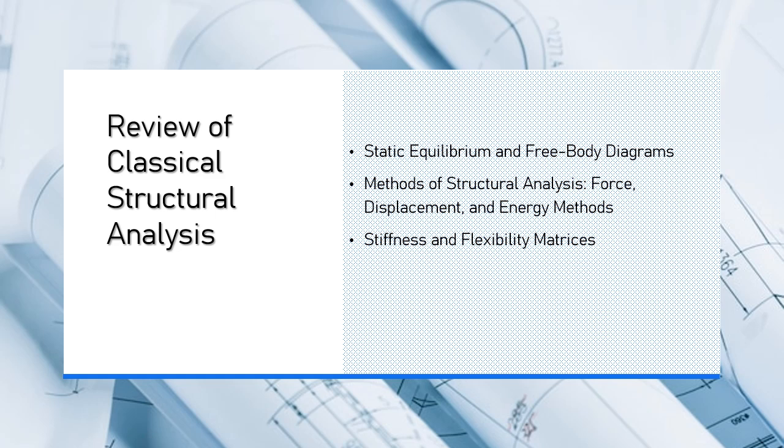2. Identify and show all forces. External forces include forces such as applied loads, point loads, distributed loads, reactions at supports, and any other forces acting on the structure. Reaction forces. If a part of the structure is supported, e.g., a beam on a column, include the reaction forces at the support points. These can include vertical, horizontal, and moment reactions depending on the type of support.